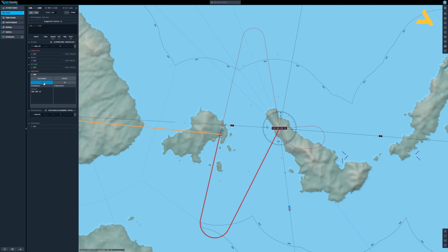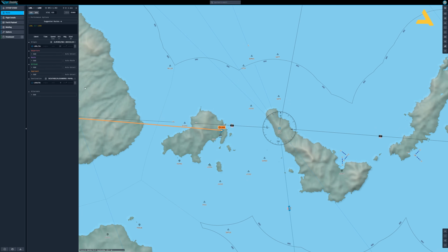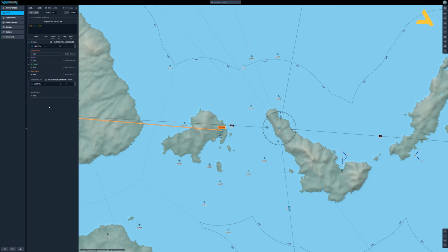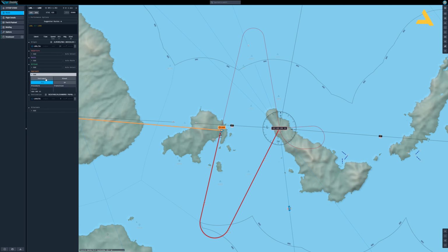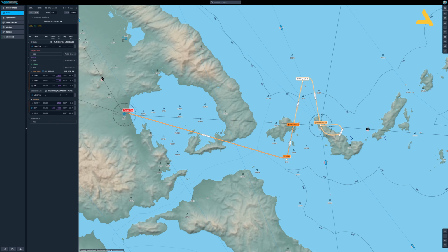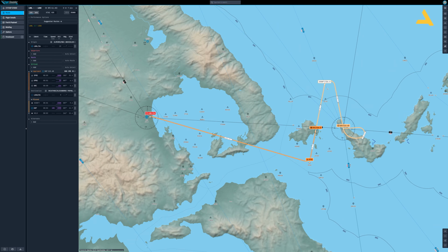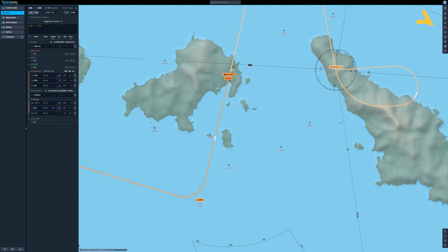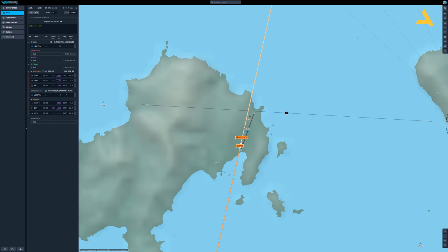So runway 1 is already selected. I can fly direct towards it. If I select it, that's it. Now I can also select this NDB DME. So what if I select this NDB? What will happen is that I can fly from this airport, I can come to this point, and from here I can start tracking the NDB, the non-directional beacon, and I will land.